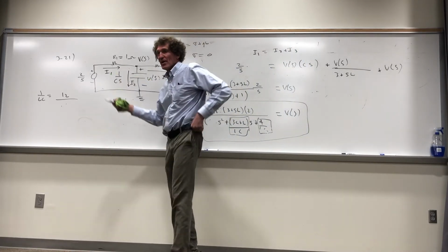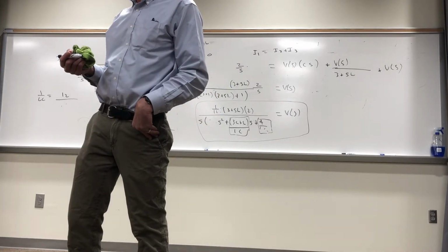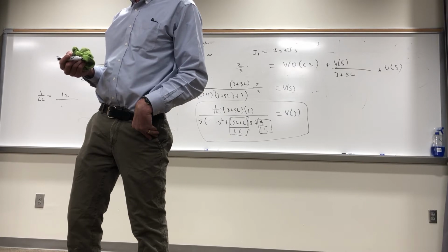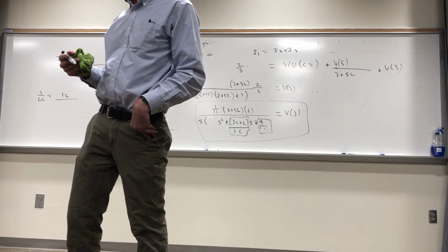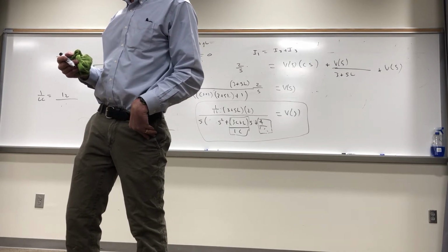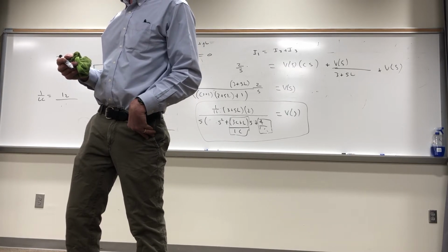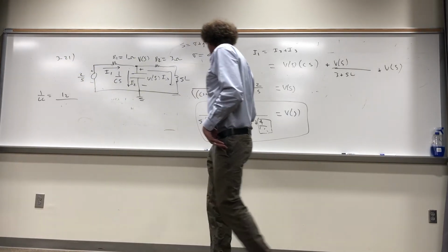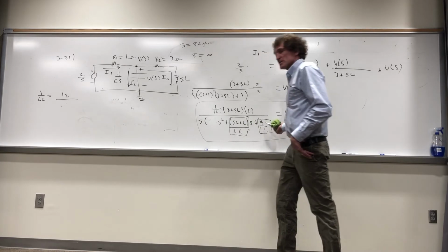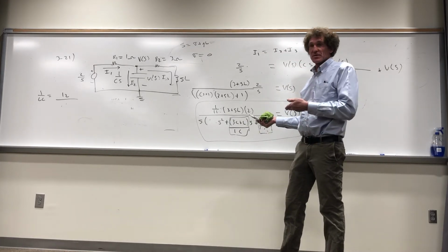I know that's 2 over. Does he have it? V of S in terms of time domain? He should. Yeah, it's 1.5 over S minus 1. No. Give me the term in terms of T. Oh, sorry. 1.5 minus 1.56 e to the negative 4t plus 0.072 e to the negative 12t u of t. And there's no sine or cosine? All right, that means that this pole here is going to be 2 simple poles. It's not going to be a double, it'll be factorable. I didn't factor it, but this is the way you go about doing it.